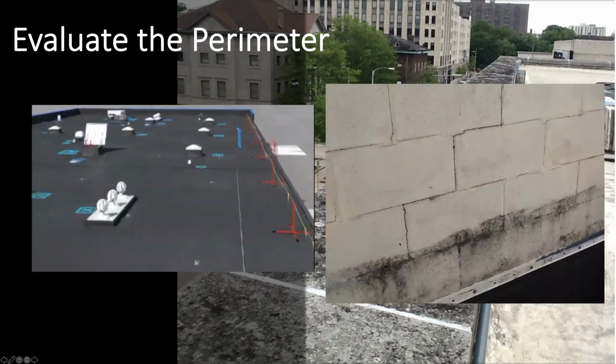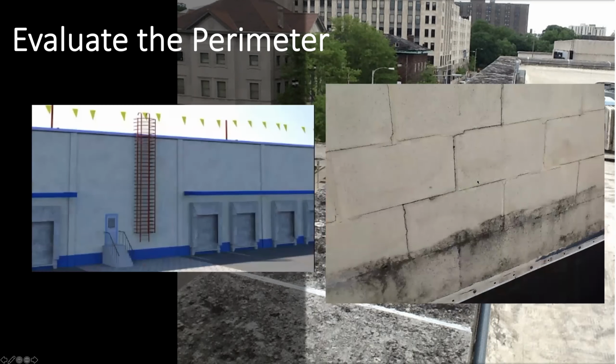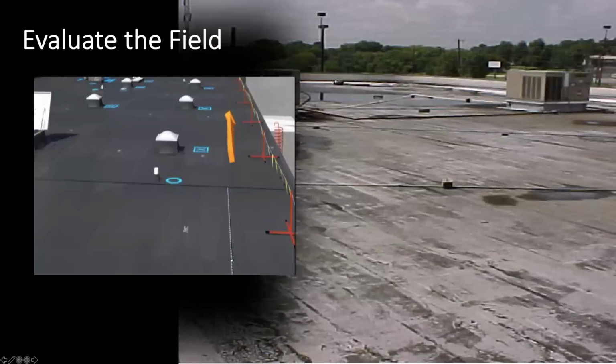Another shot of a wall. It's most likely taking water in, and again, coming behind the roofing flashings and coming out in the roof as if it were a roof leak. So definitely important to check out.